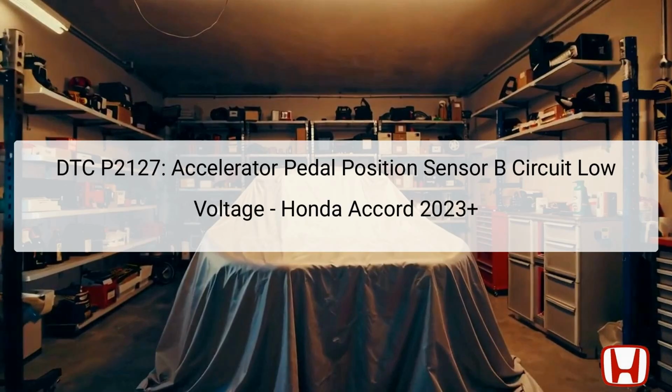The APP sensor is integral to vehicle performance, as it directly translates the accelerator pedal's position into electronic signals. These signals tell the engine management system and other involved components how much power the vehicle should deliver based on the acceleration demand. This issue can lead to suboptimal engine performance and might affect drivability or cause the vehicle to enter limp mode, affecting safety and functionality. Correct diagnosis of this DTC is essential for restoring normal vehicle operation, ensuring that the acceleration system functions correctly.